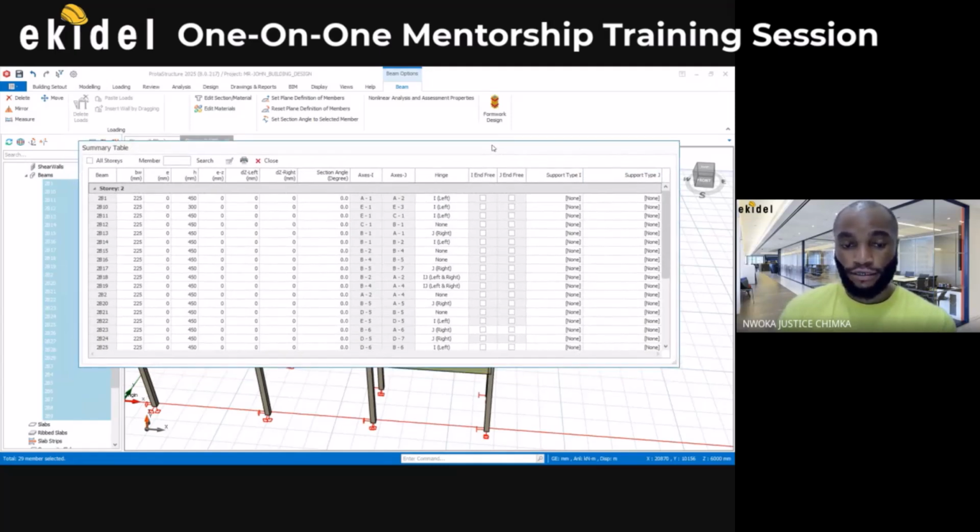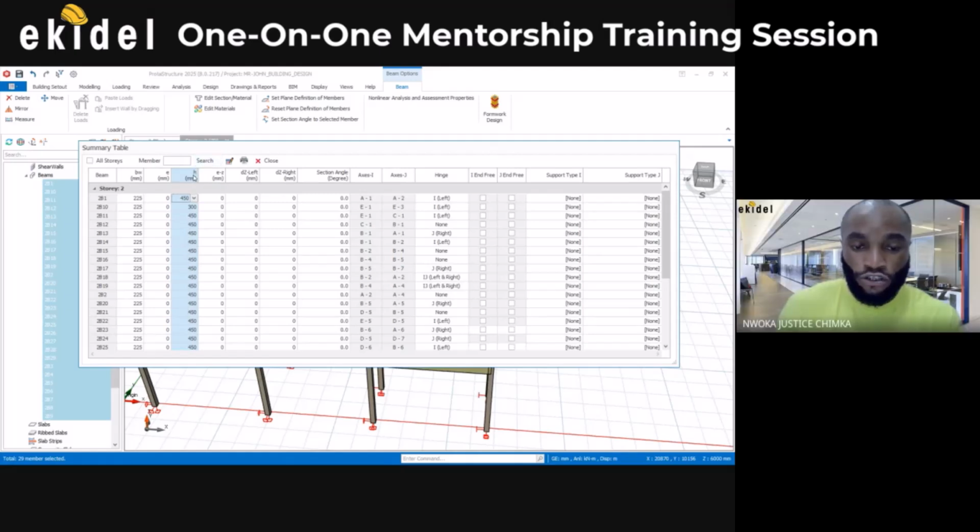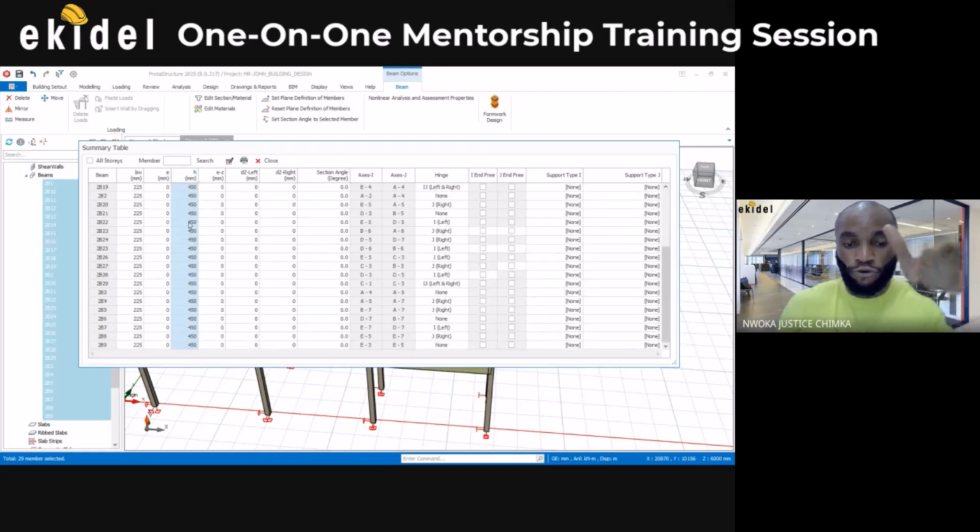All right. So with this now, you can see H here. H says the depth of the beam. So I'll click on the H here, not on any of them, on the H. That will highlight all the beams, all the depths, the complete column. Yes, correct. So just come and highlight. You can click on the H here to pick all the depth on that column.